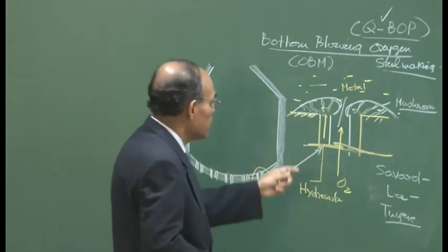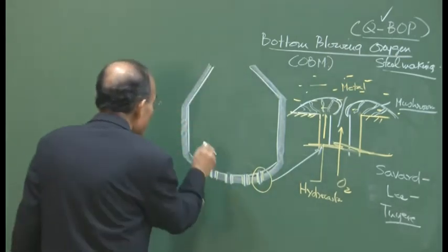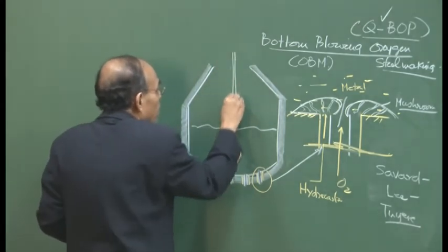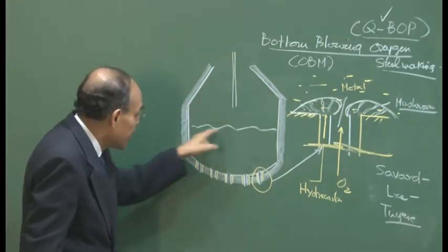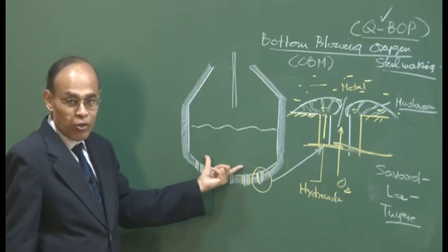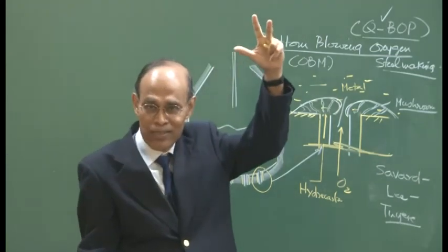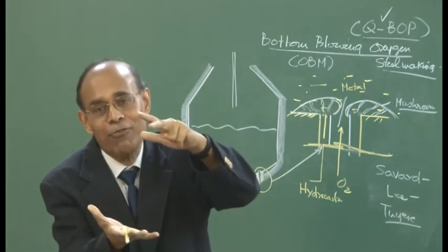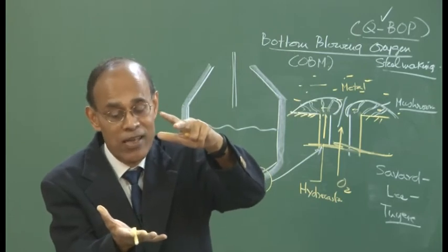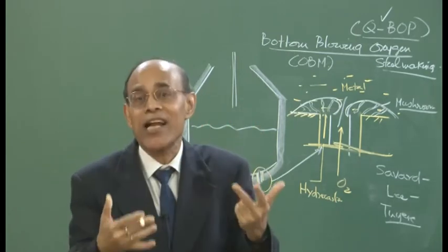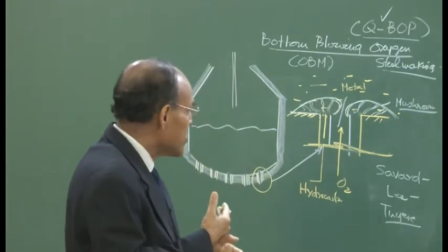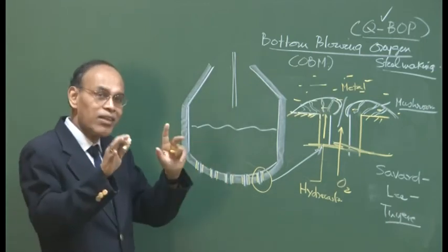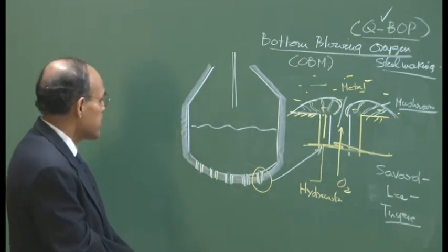Okay. Now, according to this, when you have molten metal here, now you do not have an emulsion. When you have a top jet, then you have created an emulsion, and then you have the bottom part also. There are two distinct regions in an LD converter, and I have told you that the reaction in the bulk metal phase in the LD process is not so large, because it is not quite well stirred. The energy transfer from the top jet to the bulk steel is not quite significant. So, the bulk is poorly stirred in the LD steel making process.